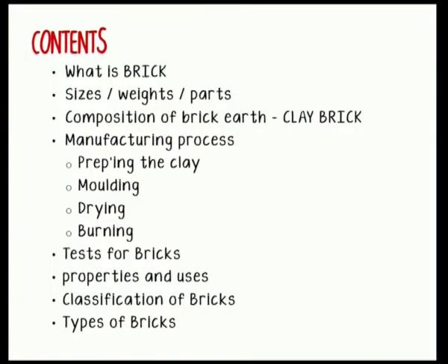In this lecture, we will be following these contents. Firstly, we will be looking at what is a brick, what are the different sizes, weights and what are the different parts of a brick. Next, we will be going into the composition of brick earth, and next we will be looking at the manufacturing process of a brick, which includes several sub-steps such as preparation of the clay, molding, drying, burning.